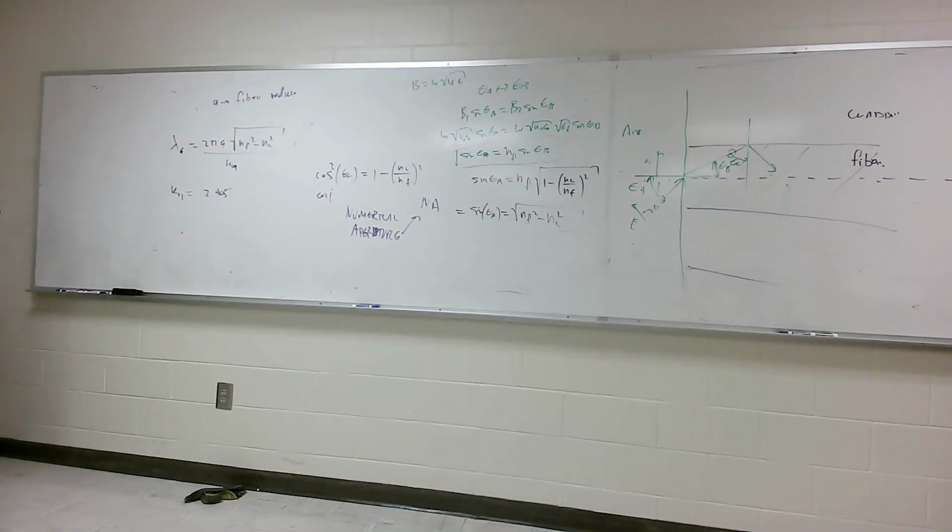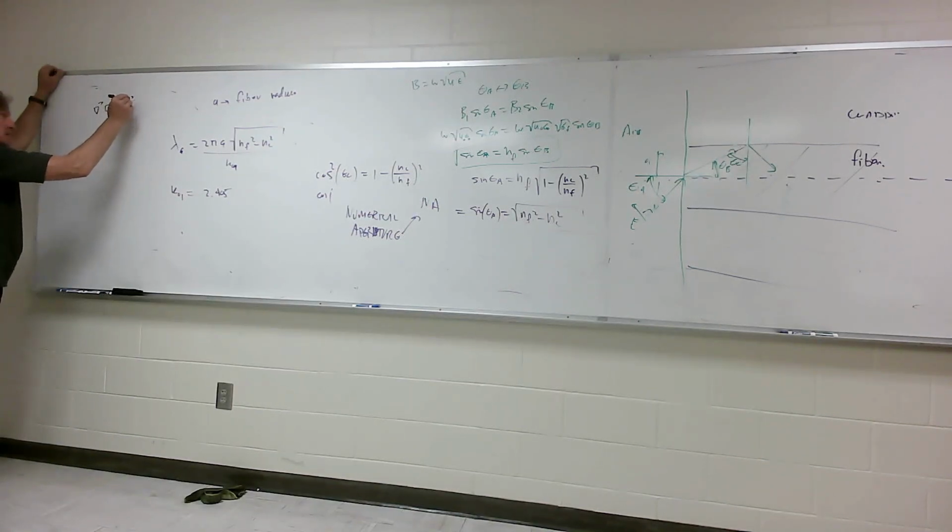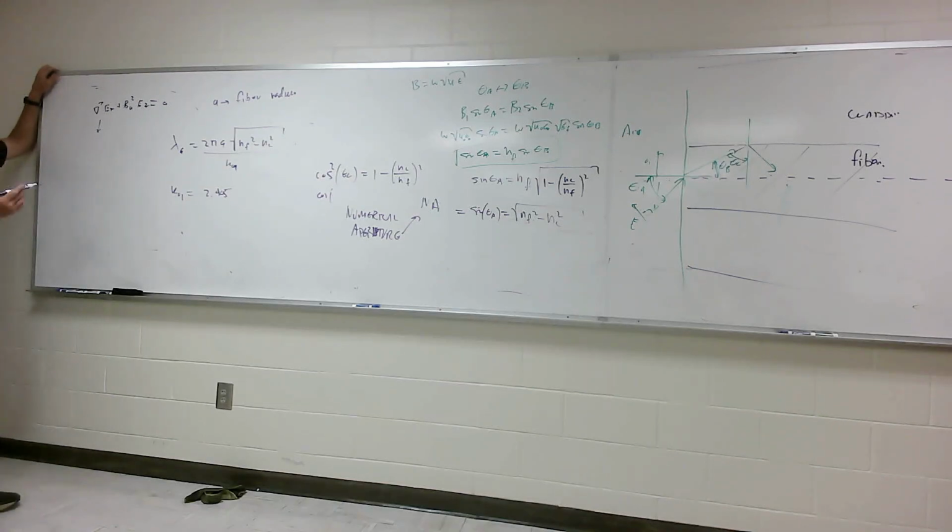So, if you think about that, if you had a fiber optic and it was cylindrical, when you do the del squared of Ez plus, I'll call it beta unguided squared of Ez, and set it equal to 0, and you solve this, when you do separation of variables, your radial distance variation, rho, remember, you got a cylinder, would have something called a Bessel function.